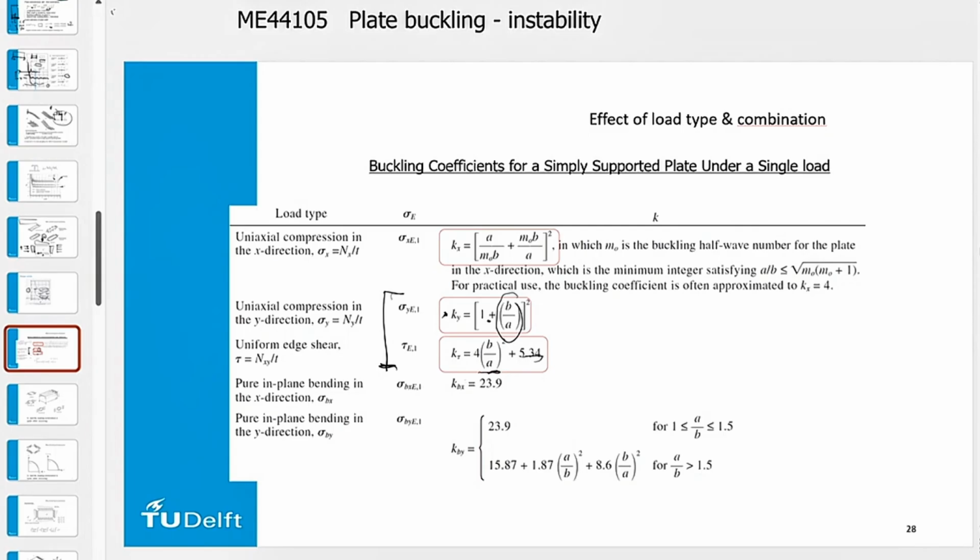So basically these curves, all standards, no matter if you use the DNV or ABS or Lloyd's or Eurocode, they basically are all based on this simple idea of comparing the buckling limit and comparing that to a yield stress. Of course, they take into account different combination factors and different safety factors based on yielding and buckling, but the idea is always the same.